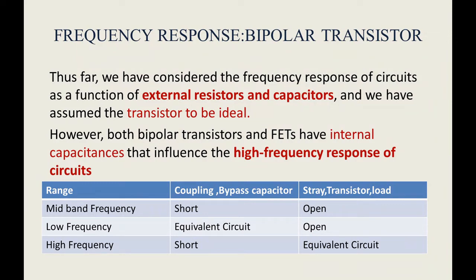Dear students, today we will see the new lecture, that is the higher frequency response of the circuit. First you want to know that over the set of different ranges of frequency, there is a limitation in your gain. That is called the roll-off function. In the low frequency, the roll-off function exists because of your coupling capacitor and the bypass capacitor.